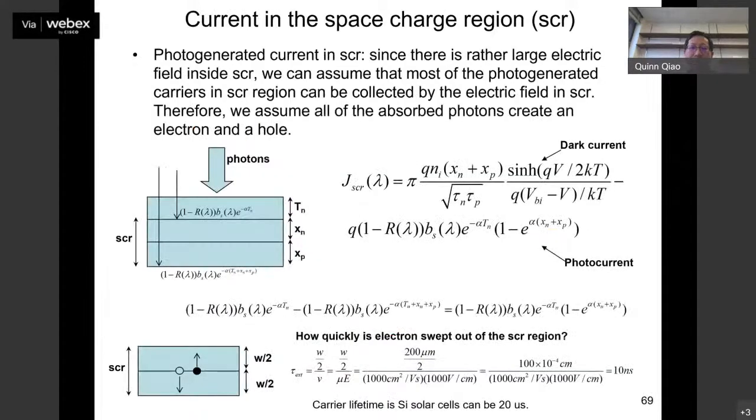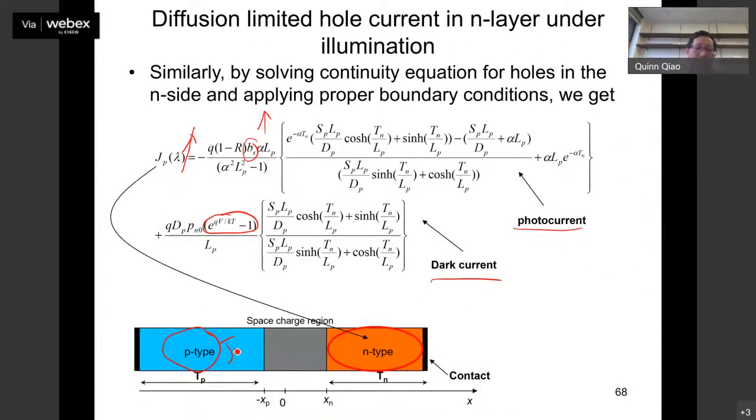Okay, good. And then you probably think about, now we talk about this JP, this GN. Now, what about in these regions? Typically in these regions, as we discussed before, you have the diffusion here, and then you have space charge regions, with very strong electric fields there. And then you either have recombination, when we talked about that two-diode model last night, that kind of recombination, and then you have another diffusion on the p side. Most of the time you will find that since in the space charge regions the charge transport is very fast, you can get very high current there. So they do not dominate the total current you will see through the diode.